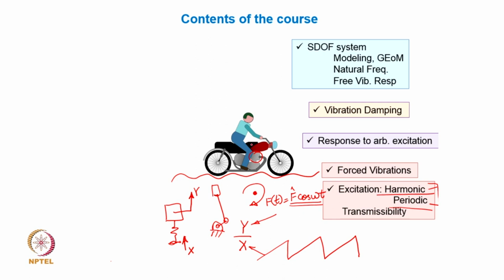On the contrary, many mechanical systems like engines or compressors, particularly in a vehicle like a car, we have engines which are mounted on the chassis. So, they are isolated by engine mounts, and when the engine is operating, it generates the excitation force, and that force gets transmitted through these engine mounts to the chassis. Okay. So, in this case, it is the force which is generated here, which if I call as F e, how much of that force is actually getting transmitted to the chassis.